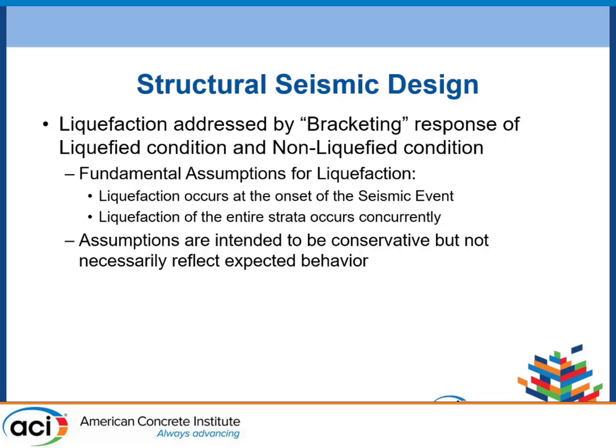One other thing that we have to consider in South Carolina is the impact of liquefaction. So liquefaction occurs when a seismic event causes the soil to lose its shear resistance, and essentially you get a much weaker response from the soil and you lose some of its capacity to resist load at certain locations throughout its depth. We make some assumptions about how that liquefaction is handled. These assumptions are not always consistent with reality in the sense that we know that there are variations for how liquefaction actually occurs in the substrate. But we have chosen the assumptions that we have to be conservative relative to what will happen.